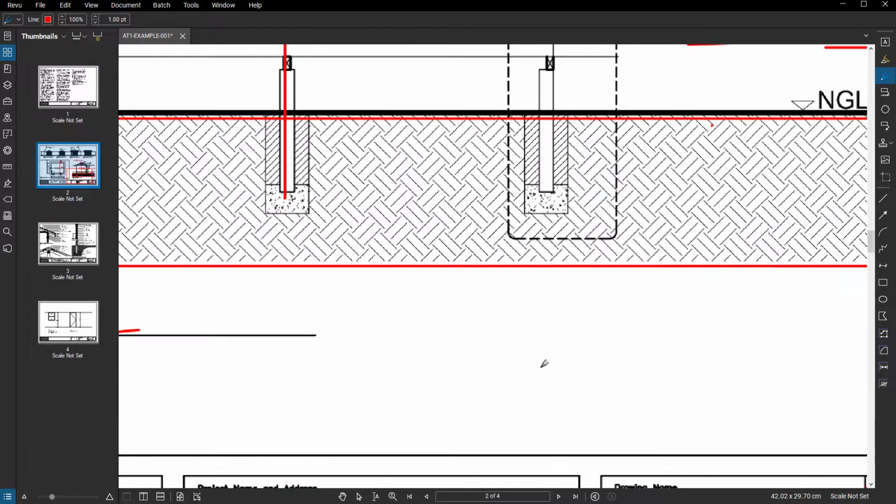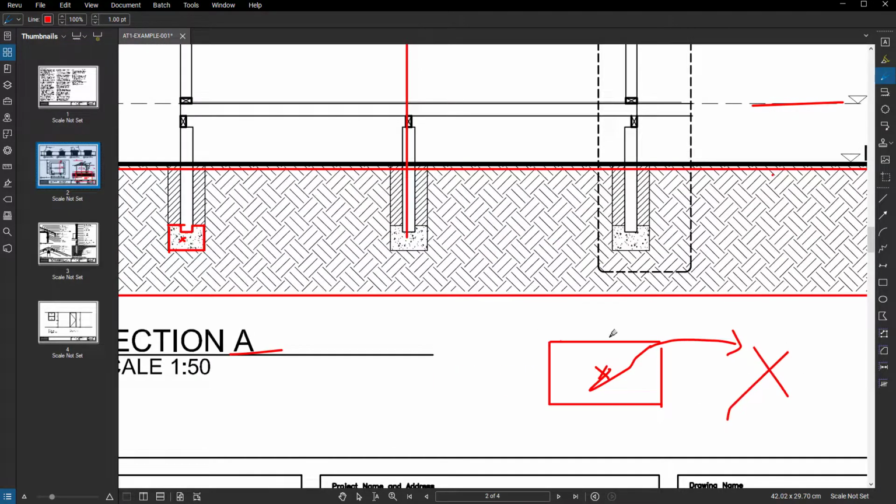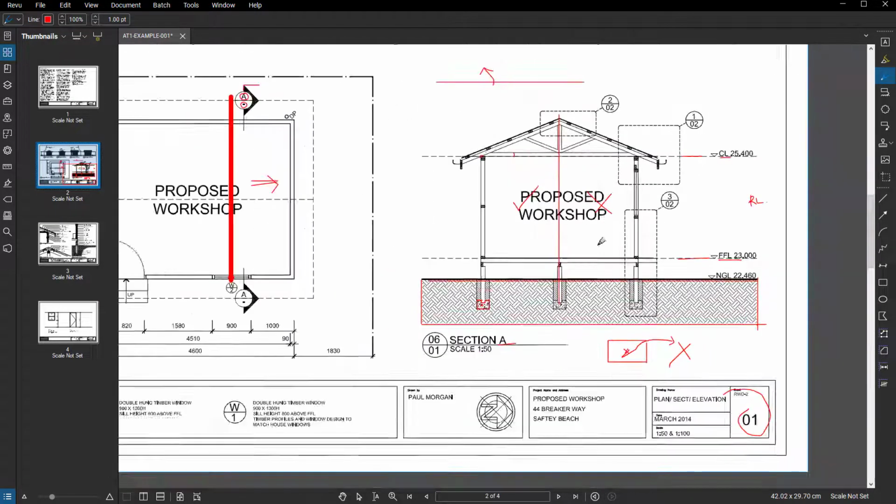A good tip for you though is make sure that your lines or your boundaries are closed. If we had a box that looked like this and it was open just here, AutoCAD wouldn't understand that this was the area I wanted to hatch. It would see that area is open and think, oh, okay, you want to hatch the whole drawing. And that will immediately crash your file, undoubtedly. So you have to be very careful that your polylines are closed. And the other thing too is a good tip for you before using hatch, always save your file. Save your file before you start hatching.